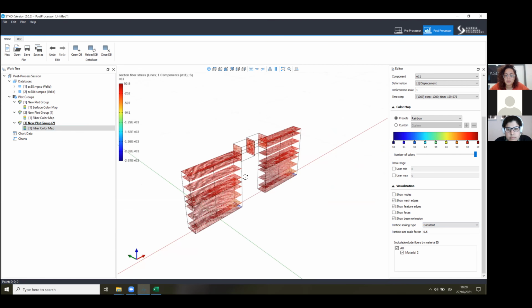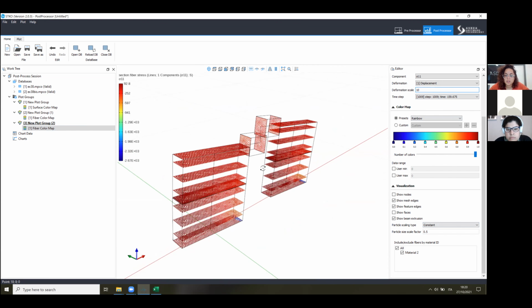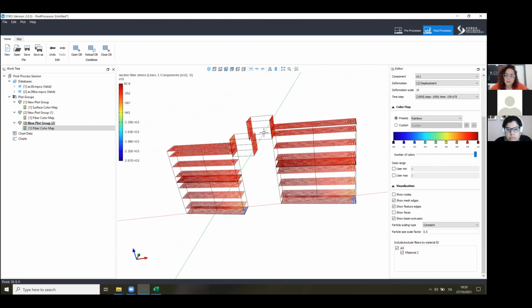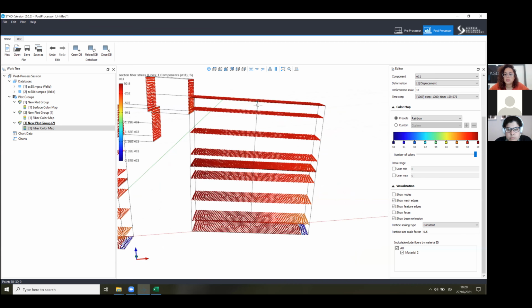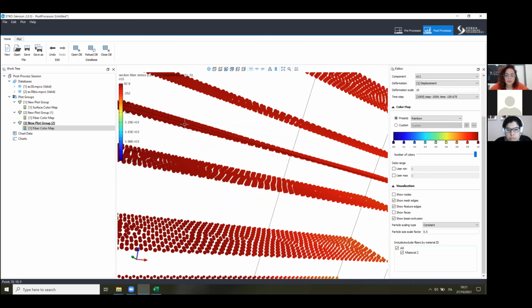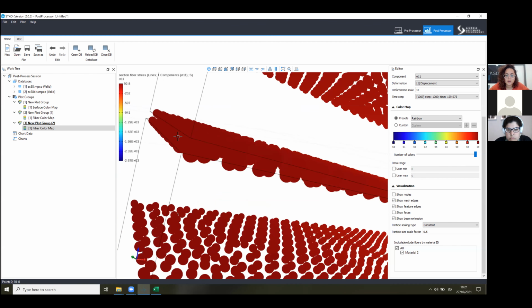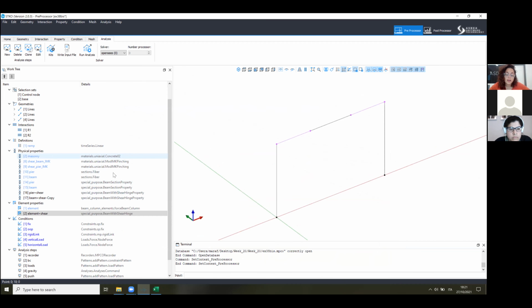And this is more realistic for masonry, because if you think about it, what is happening in masonry is starting maybe diagonally on the corners, but it's also working in the center of the element. And it's not like RC structure where you can assume that mostly shear failure will happen in the joints. So as you can see, even here, there's a bit of sliding of the two elements. So these are two different approaches that you can use to model with a three frame model and distributed plasticity in terms of shear behavior.